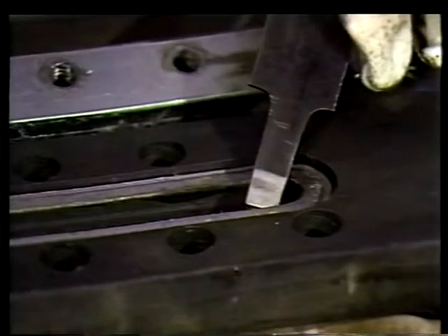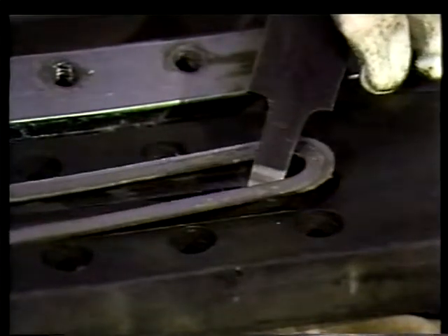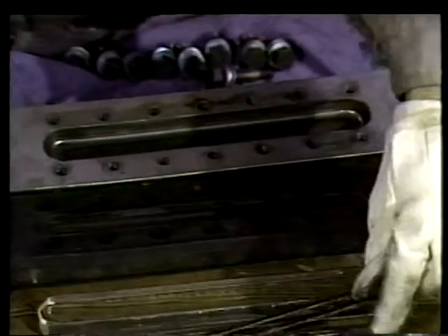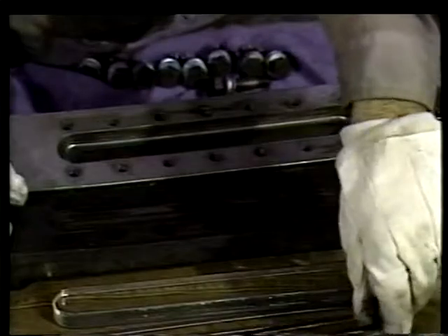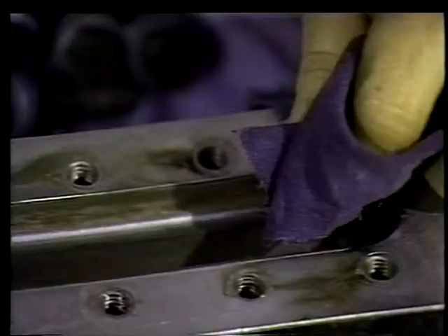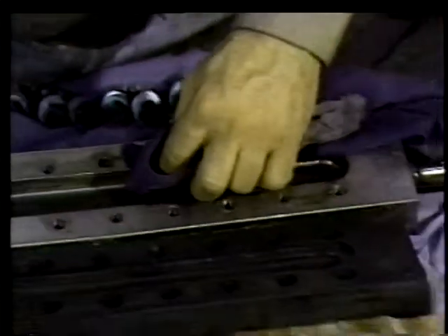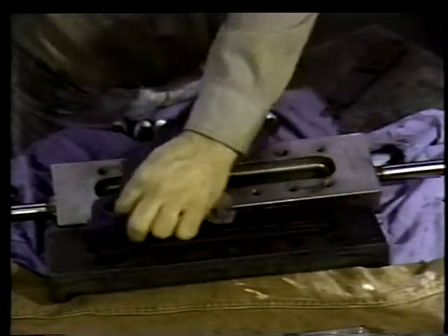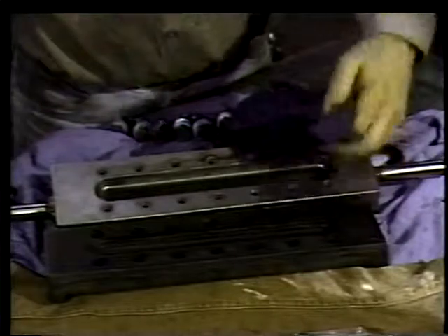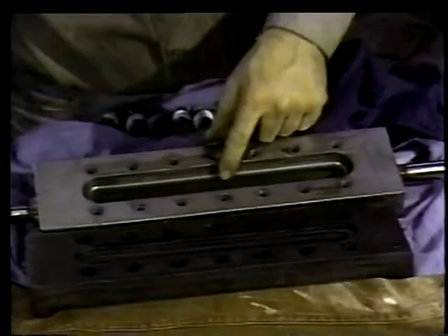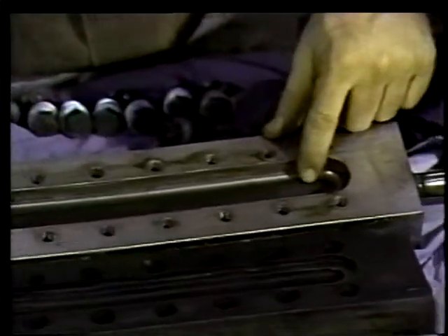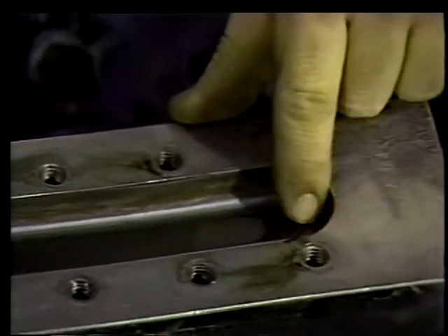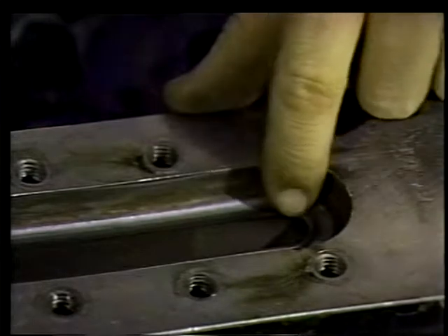Then remove the cushions from both cover plates. Be very careful, since even a small nick or scratch underneath the cushion gasket may eventually cause that glass to crack. After you've cleaned the gasket seating surfaces and cushion seating surfaces, inspect the gauge body and both cover plates. Check the seating surfaces for cracks, nicks, scoring, dirt, and pieces of the gasket. Also look for cracks and corrosion in the rest of the gauge.